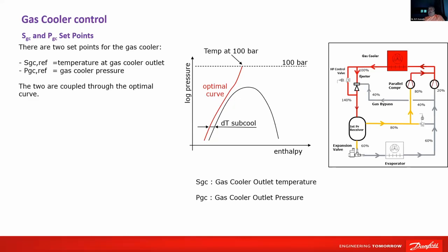It's a very good question, but there is no simple answer. I will try to explain it this way. You are only seeing one compressor here. We can have up to 4 MT compressors and 4 IT compressors. That is parallel compressors, which can also be of dissimilar sizes or the same size, which means when you are running 4 compressors or 1 compressor, the capacity is different. All this is managed by the controller. Now, how do you manage it?